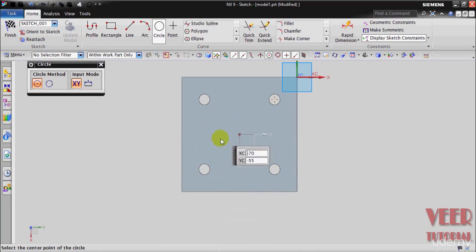Then I need the center of this square. So we cannot trace the center easily. So to trace the center, we can intersect the midpoints. Midpoint of this line, I select midpoint and trace it. Okay, we can see the dots here. Then also the midpoint of this vertical line. Then I trace this and the intersection will be center. Here I can insert the values 30 and 15.